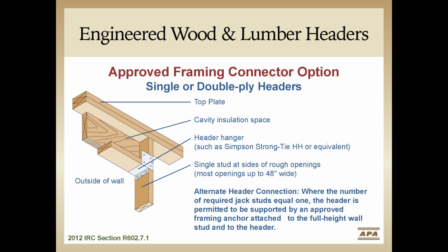This is a method to eliminate the jack studs at openings, and it's using a header hanger. Again, this would optimize material usage and provide for more cavity insulation. One thing to keep in mind with this is the metal connector could create a thermal bridging concern.